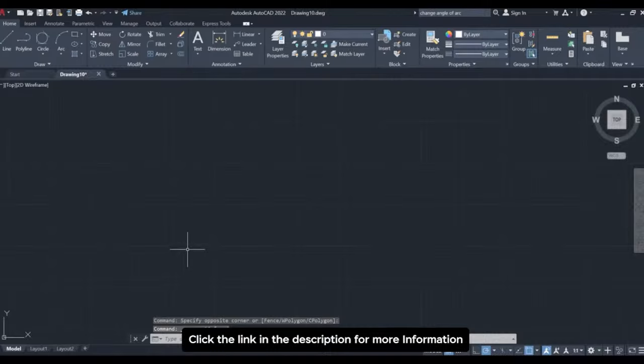Moving on, we now talk about arc, another important tool which is necessary when you're trying to create any of the engineering curves. So arc can be accessed using A, enter for arc. Arc by default, please remember, gets created in the counterclockwise direction. That means in this direction, like the way I'm moving my cursor. So only the first basic arc, which is the normal 3-point arc, works in this manner, where it asks you to specify the first point, click anywhere, second point here, and third point here.